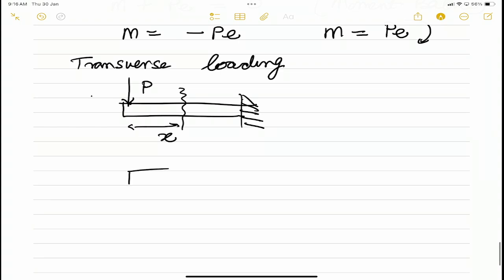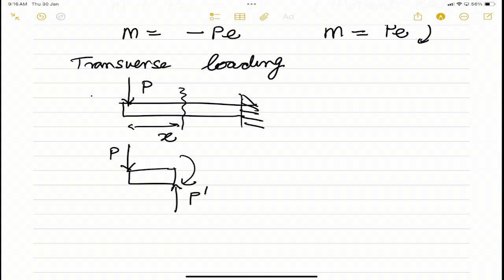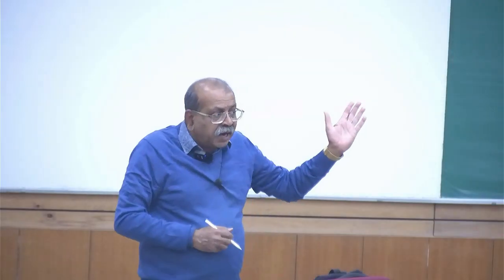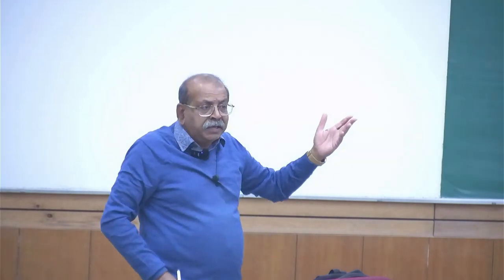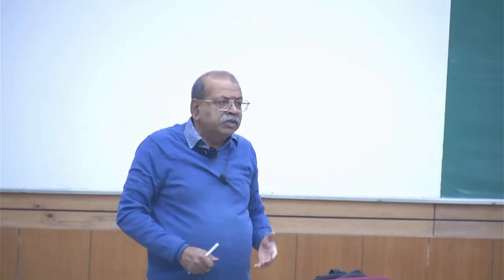Now, if I cut this section at X, and once again if this is force P, so I will get on the cut section a moment M and a force P. So again, I get a bending moment, and the results which we get for pure bending, we will extend them and use them in these cases.